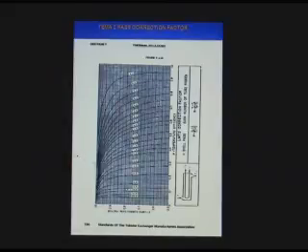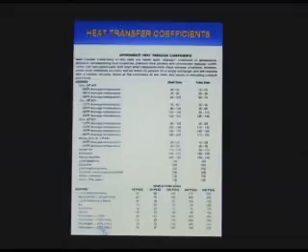There are other combinations here. You can have a 4-path tube side. That will have a different correction factor, so you need to be aware of that when you're looking at the different designs. The HTRI program will basically account for that for you. It will give you a corrected LMTD, and it will also give you warnings if you're in the marginal range. If you can read that, it's also in your table. I believe I handed that out. No, I didn't put that in there.